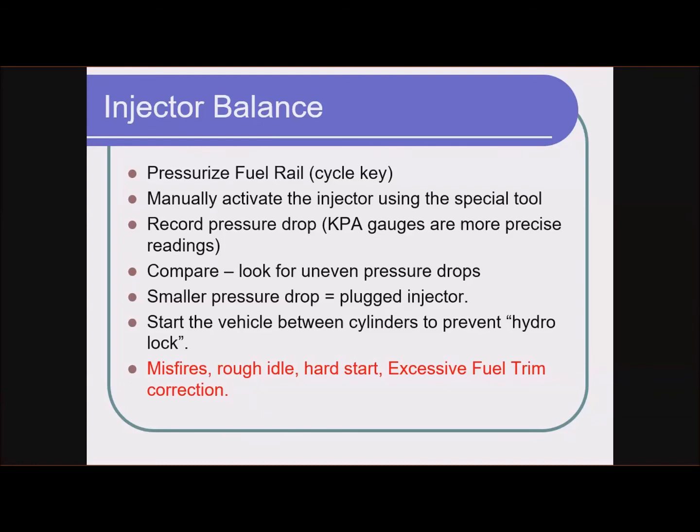Some things to be cautious of: every time you fire that injector, you're putting liquid fuel directly into the intake manifold. You almost need to start the engine between every cylinder just to clear out all that fuel, or you'll be flooded. Or even worse, if you do one cylinder multiple times, you can actually hydrolock the engine. We had it happen.